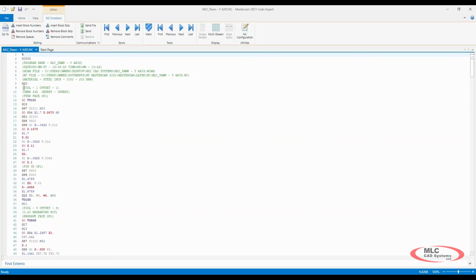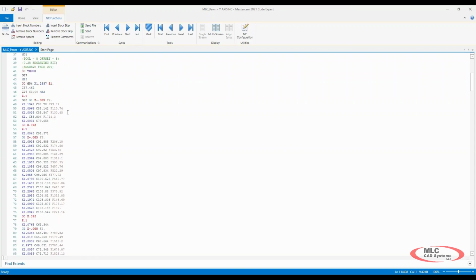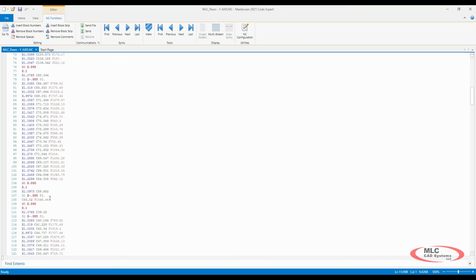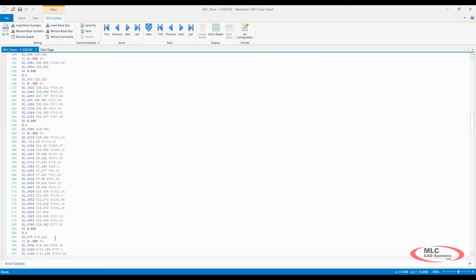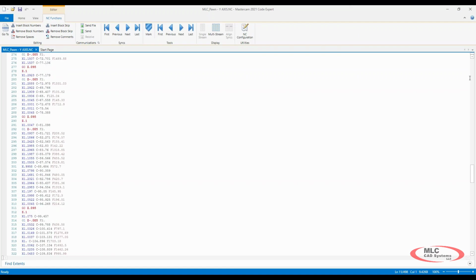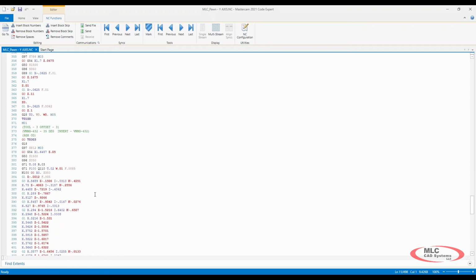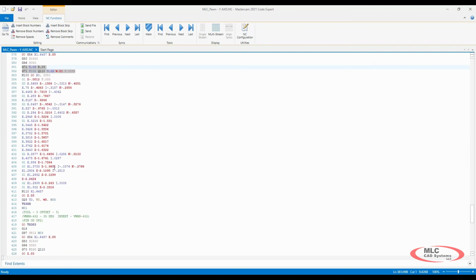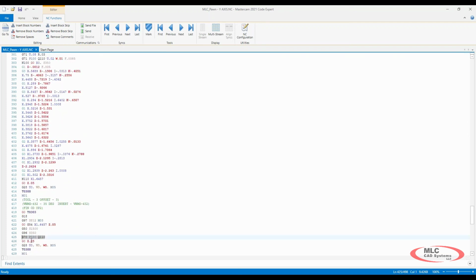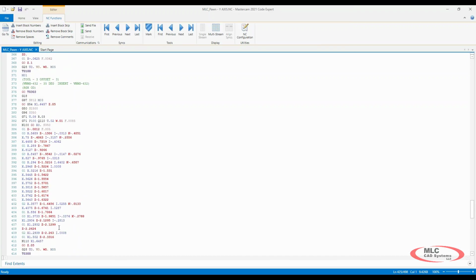And Mastercam Code Expert is going to open up. And one thing you'll notice is all these comments that we had. It's bringing in comments for our tool number and offset number, and also the comment we had for the operation. And we have our longhand code. You notice the C-axis motions. It's going to be our engraving. And let's go ahead and scroll down to Op2, and you'll see the difference between our CAN cycles now. We have our G71 and our G70s reading block 100 to 110.